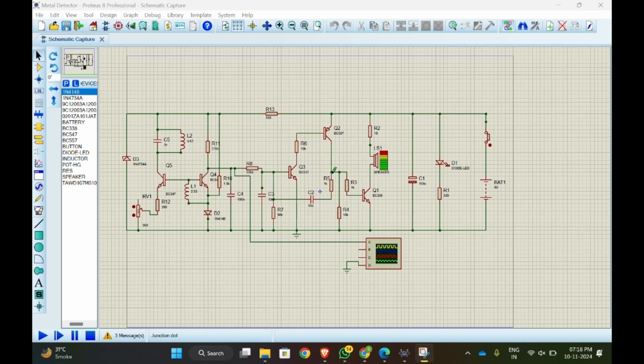The output of the oscillator is connected to a driver transistor via a 1 kilo ohm resistor. The resistor prevents high currents flowing when both transistors are turned on. The driver transistor is directly connected to an 8 ohm speaker. The 18 ohm resistor reduces the volume and prevents large spikes appearing on the power rails. The result is a clicking sound.